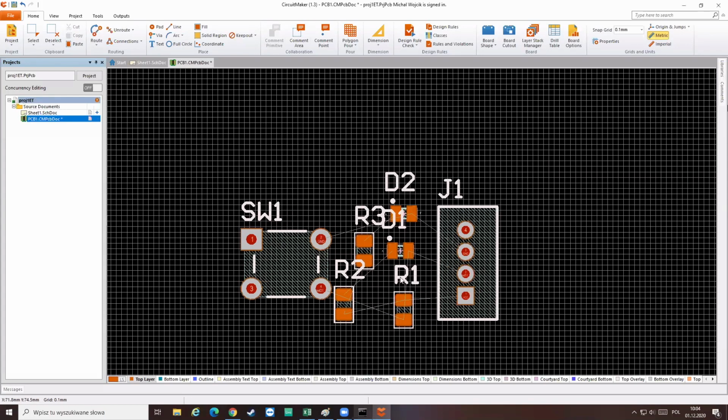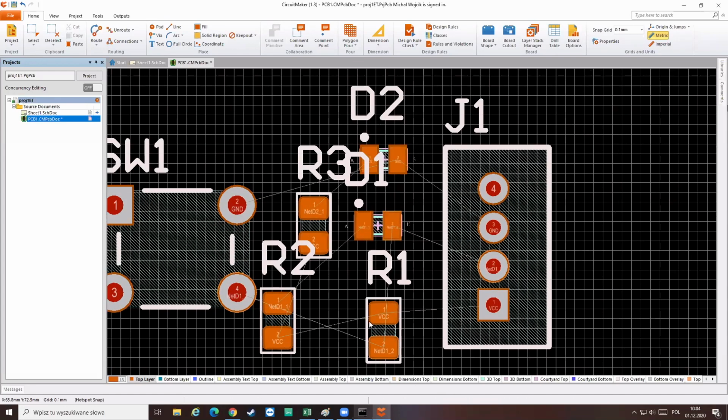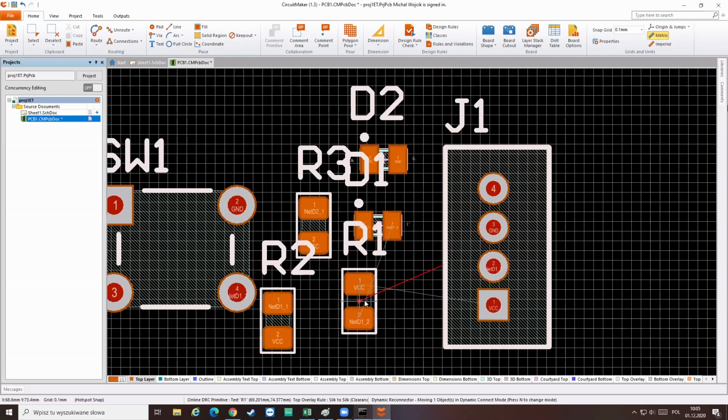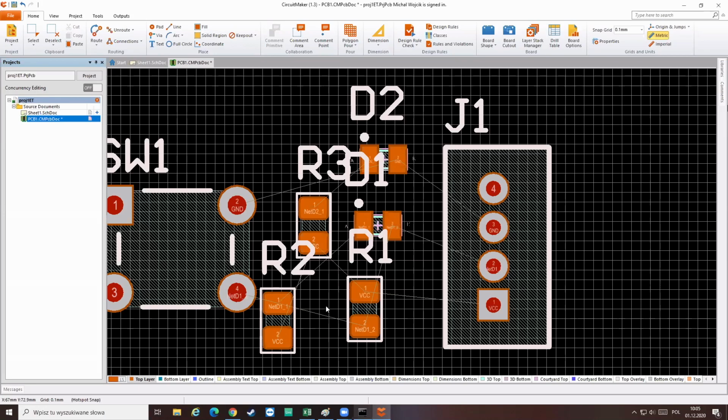Altium is showing you the final connections, which paths or vias or drills have to be made later on, with these little lines, I call them spider webs, because they look like that. If you move an element, it shows you with these little gray lines where in the end it's going to be connected. Of course, it might not be perfect. It's showing the shortest way. Sometimes we go around and it works for the design, but it's still showing the shortest way.